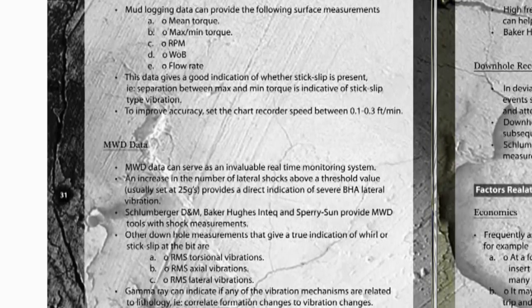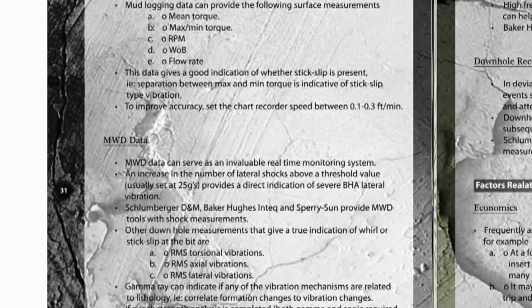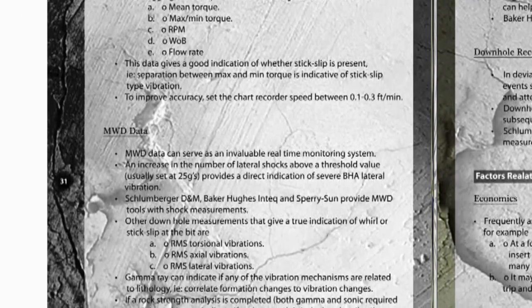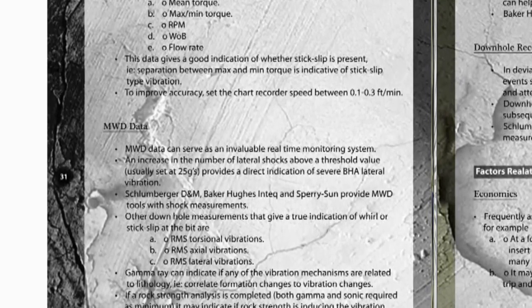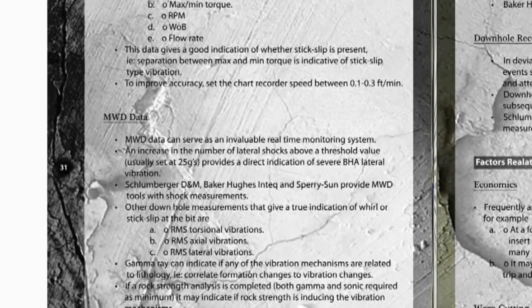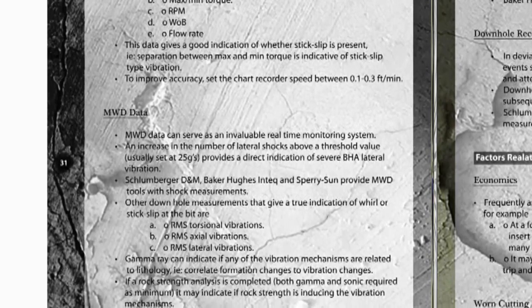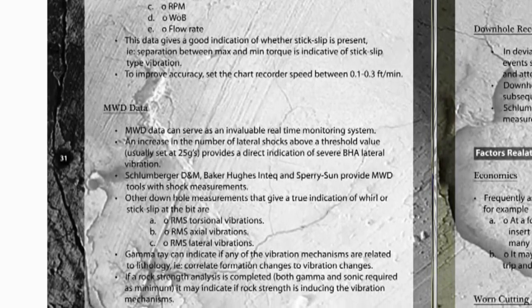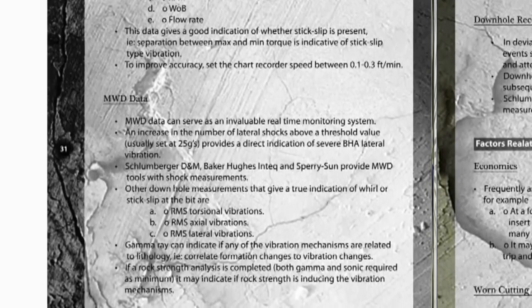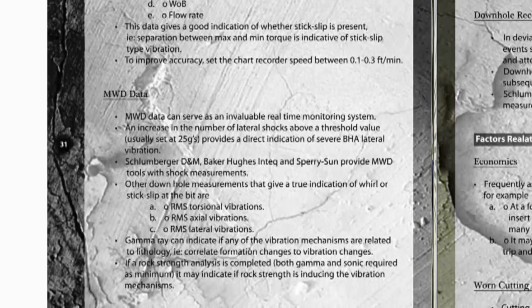MWD data can serve as an invaluable real-time monitoring system. An increase in the number of lateral shocks above a threshold value, usually set at 25 Gs, provides a direct indication of severe BHA lateral vibration. Schlumberger D&M, Baker Hughes Intech, and Sperry-Sun provide MWD tools with shock measurements.